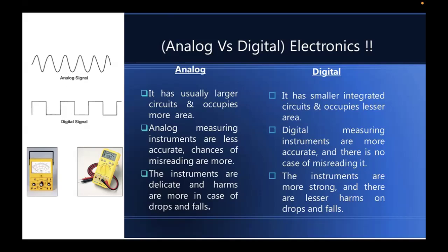But if I tell you, okay, we have only two states, 0 and 5, and you receive a signal of 4, now the probability that this 4 belongs to the 5 state is very, very high with respect to it belonging to the 0 state. This is simply the concept that when you minimize the states, you maximize the probability and you have better noise immunity.